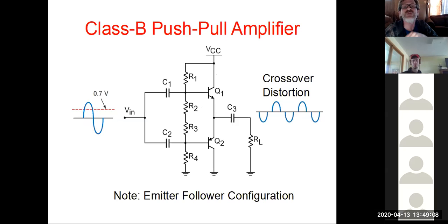So here we see a little more complex push-pull amplifier. Notice that we're using the emitter follower style, but notice that on the output, this one experiences a certain degree of distortion. They try to balance that out with the capacitors, but in this case, you're getting a lull in between the two, if you will. So we don't get a clean output in this case.